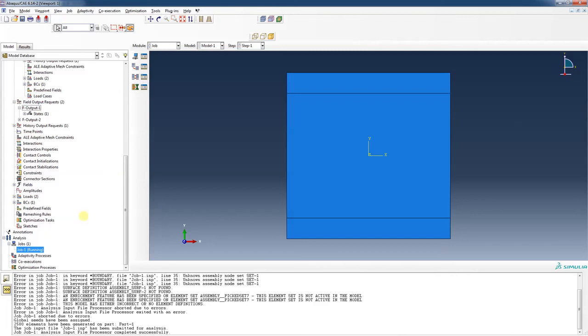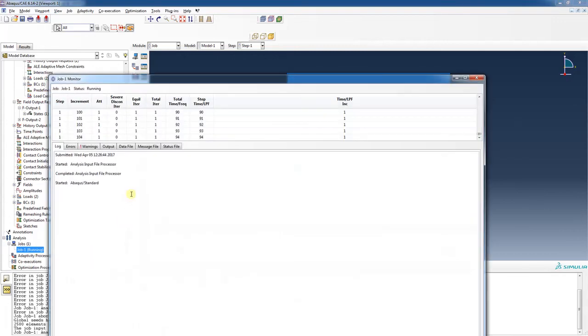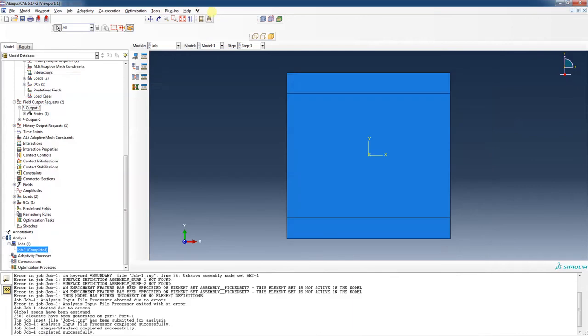Okay, so this is running. We can even monitor this if we want. It's pretty common to see these fail if your stresses are too high. The crack gets to be too large. It runs into a boundary or something. It looks like this one made it. Let's see if it initiated a crack. It may or may not have.